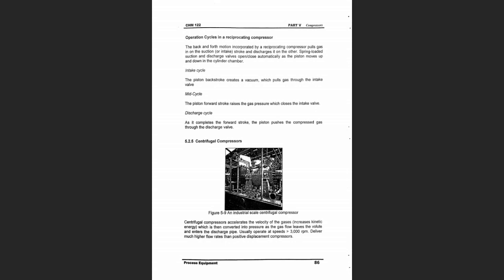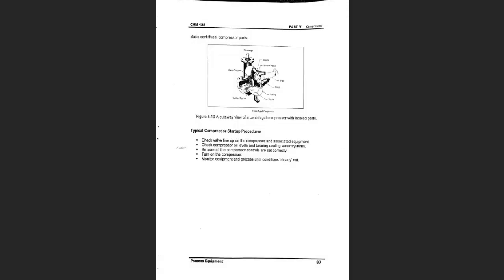And the description of the compression process is exactly the same. We have the suction, and you all know how it looks like. As the impeller rotates, and with the vanes you have on the impeller here, that gas will be pushed from the center towards the edge of that impeller, and that causes the kinetic energy to increase.